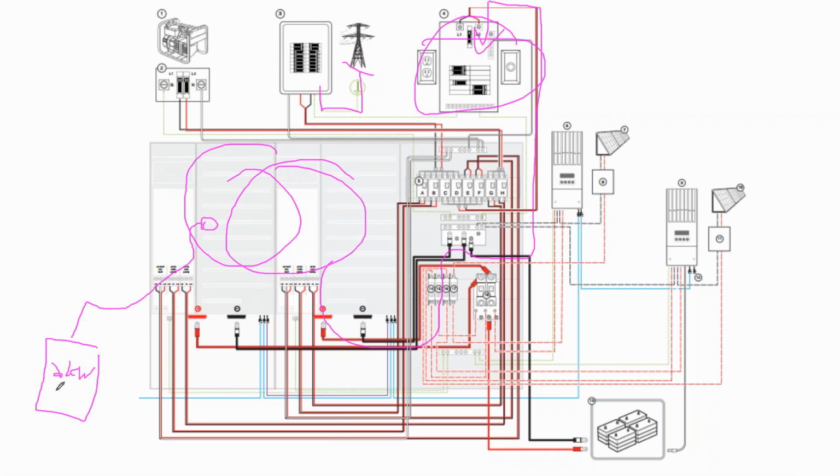Like, oh man, that stinks, because if I lose power during a blackout, I want to power my entire building and not just a critical load panel. But code says your backup system has to be able to supply the loads that it's trying to power. So you have to do a building level backup system to supply building level backup power.